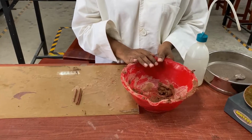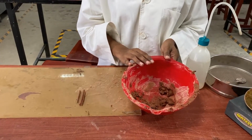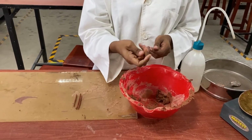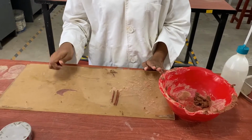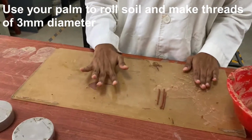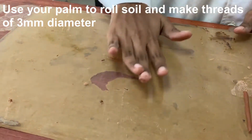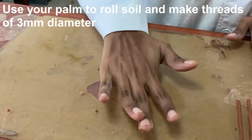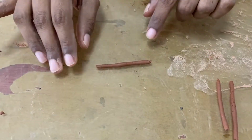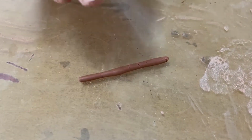Now we are going to determine the plastic limit. In order to do that, we have some soil sample with a little moisture added. We will have to take peanut size balls, right, onto a glass plate, and using your palm you may make threads. Each thread you make should be around 3 millimeter in size. As you can see, there are some cracks formed. When these cracks appear, you may stop rolling.